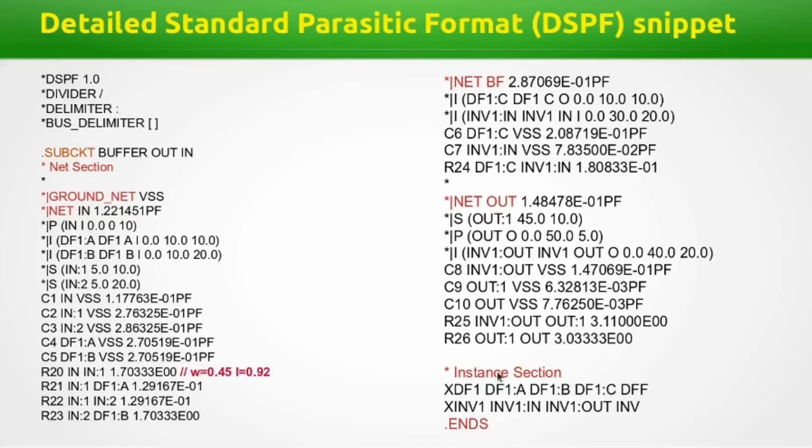So this is used in a SPICE simulation directly. Here the SPICE instances of the different internal parts will be there, and there is a .ends at the end. So this ends the SPICE sub-circuit. This is for a buffer, right? So the sub-circuit buffer ends here.